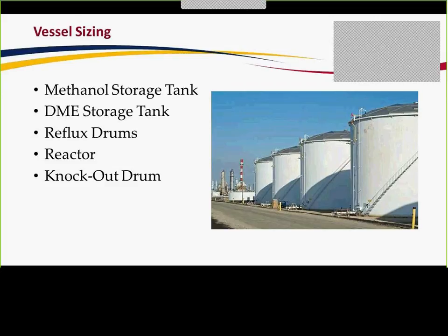For the DME storage tank, we wanted to ensure that if there was ever an error throughout the process that required shutdown, we had some methanol or DME stockpiled on site to keep supplying the trucks with fuel. So for this, we considered a 5-day stockpile time.